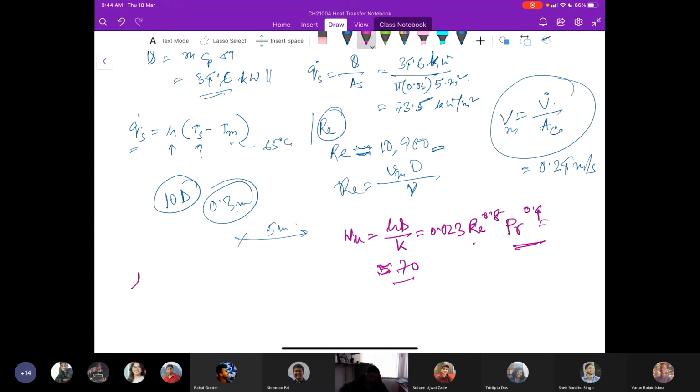So now we can calculate my H, which is K by D multiplied by the Nusselt number. And that comes out to be... Are you following? Yes, sir. So what is the H value? H is coming out to be around 8.878.